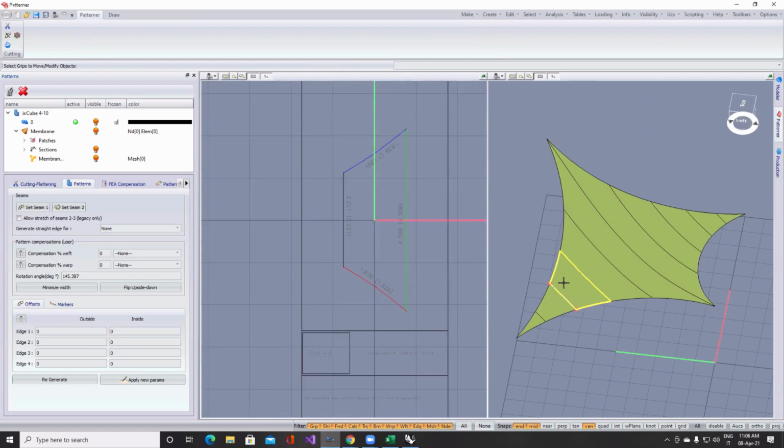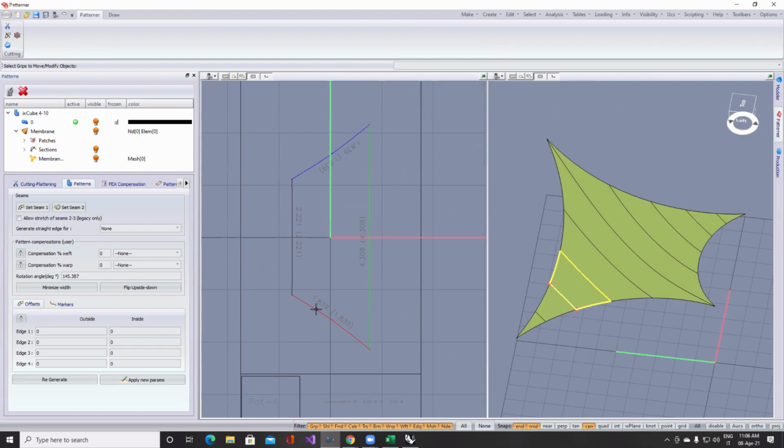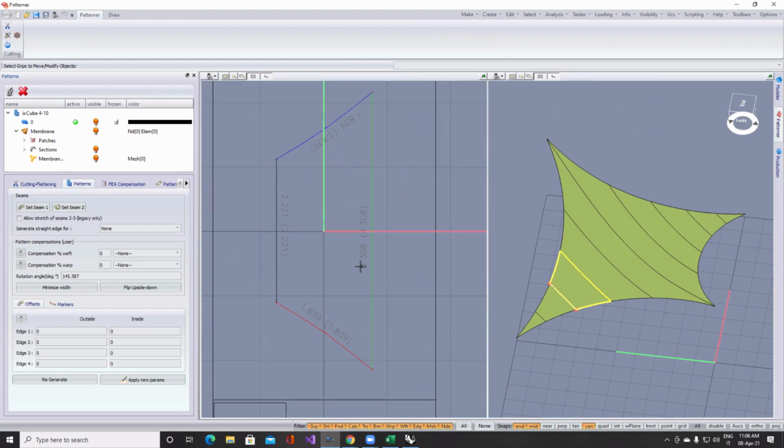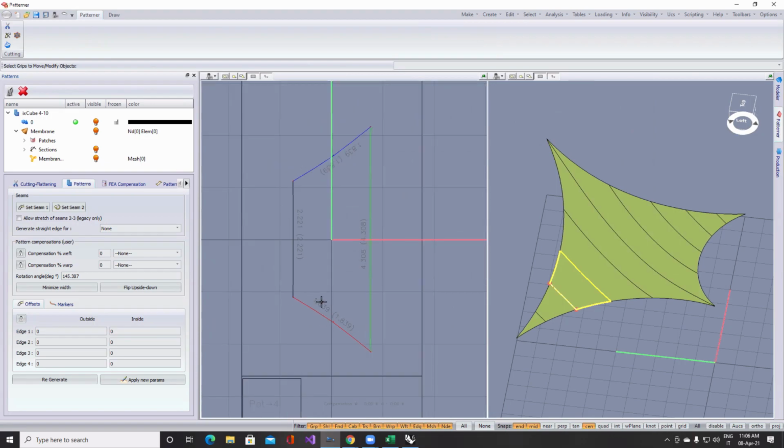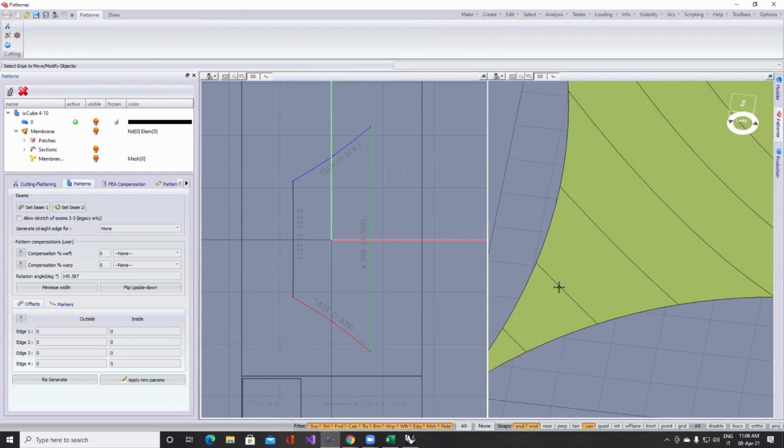In this case, it has detected the edges. Generally speaking, we have 4 edges in a panel. We have always 4 edges. We call these the main developing edges. We see them here, green, blue, red, and black. Why do we want to use these edges? Well, they are comfortable for the simple reason that generally we want to check between 2 consecutive edges if they're weldable. When we go into production, I want to see if 2 edges have the same length, because they have to be weldable.